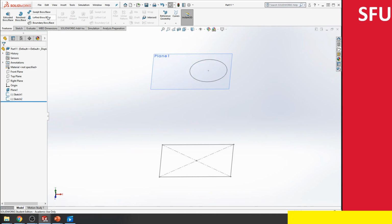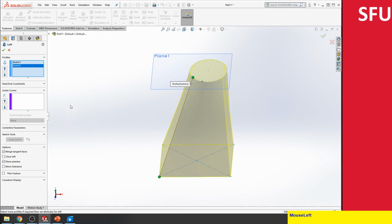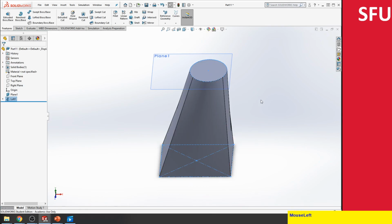We're going to go loft, and then select the profiles, and sketch 2 is going to be this one over here. Then it creates the loft. I can potentially add guide curves, and you can give start and end constraints about how the shapes will behave. But this basically creates a lofted shape where you're transitioning from one shape to the other.